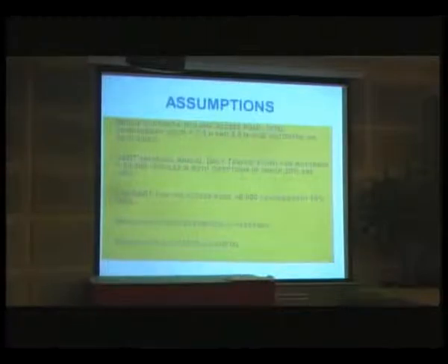So as far as the bridge was concerned, it was supposed to carry a two-way access road. So the carriageway width would be 7.33 meters, and there was an additional requirement that there should be 2.5 meter wide footpaths on both sides. We assumed that the motorway had a traffic flow rate of 80,000 vehicles in both directions.